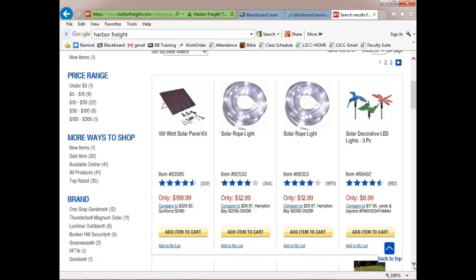So it says that it could put out that many amps. So it's 6 ampere hours. That means you could put 6 amps out for an hour. And then you could say it could put out 12 amps for a half hour. Or, if you had 3 amps, you could run it for 2 hours before it discharges. So batteries are rated in voltage, but they're also rated in a discharge rate. They call them ampere hours.